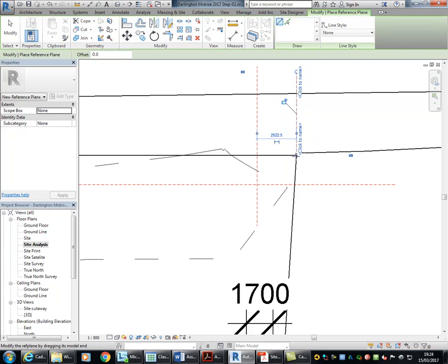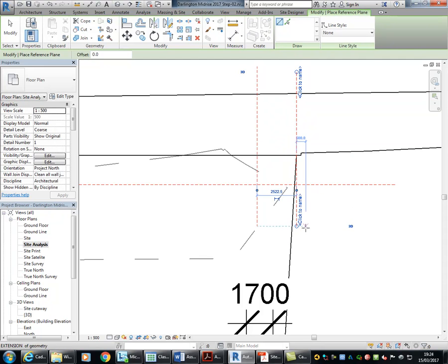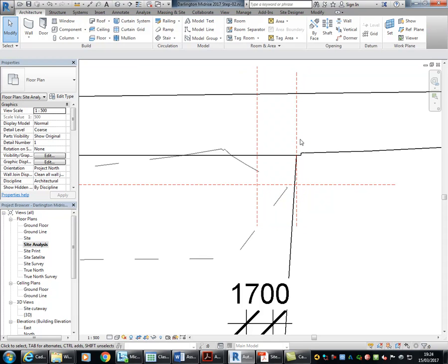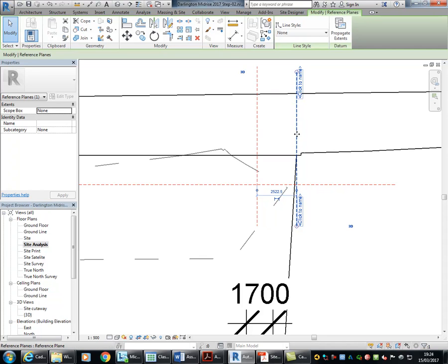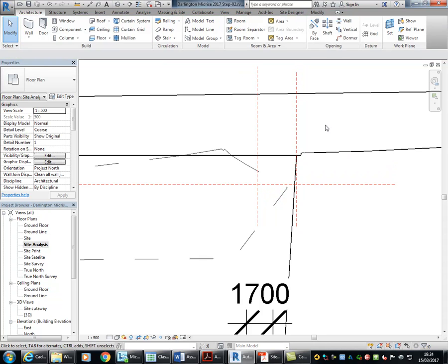It's typical actually when you have boundaries that aren't at right angles. That means pretty much every boundary. It's very rare to find boundaries that are at right angles. Then you'll often need to dimension from those boundaries. But you're not dimensioning usually from the angle of the boundary. You're dimensioning from a corner point, and you're dimensioning orthogonally at right angles, and that's what I'm doing here. So by drawing a reference plane through each corner of your property, then you give yourself a thing that you can set your dimensions out for. So it's quite typical to have reference planes drawn at each of those corner points.